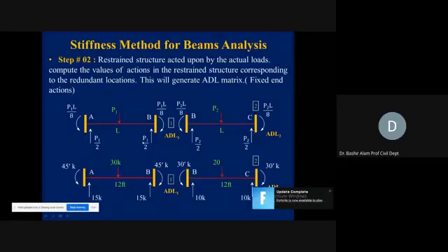So for that case, the bending moment now produced at each end will be equal to, let W be the intensity of the load, so it will be WL squared divided by 12. And the vertical reaction produced at each support will be equal to WL divided by 2. So that is another general case now. Similarly, now you can find out for the triangular load, or if a couple is applied, and we already discussed those general cases in module 5.